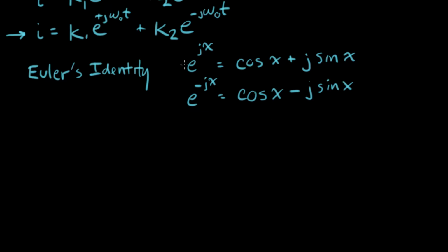So these are useful because we have this exponential function with the complex unit inside of it. When we go over to this side, this is a sort of a normal complex number. Cosine x is some number between plus and minus 1. Sine x is some number between plus and minus 1. And it's just a normal complex number. So this may help us simplify our life here as we move forward. All right, so that's a really important identity that we get to use to solve our LC circuit.